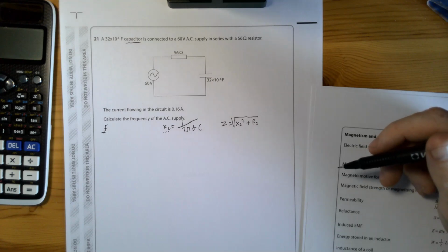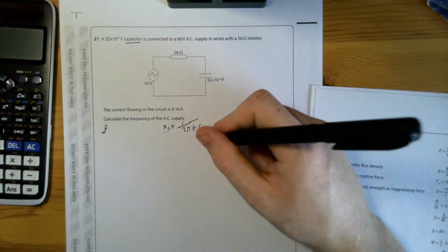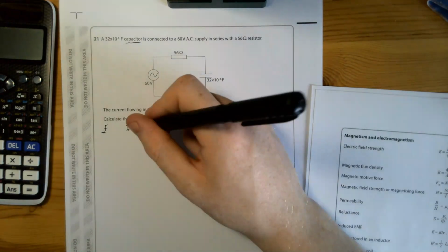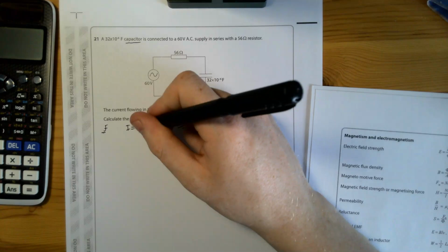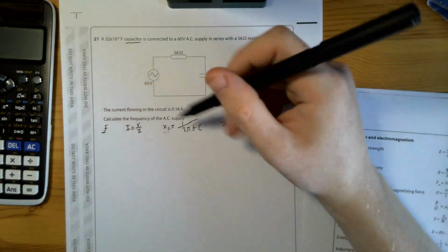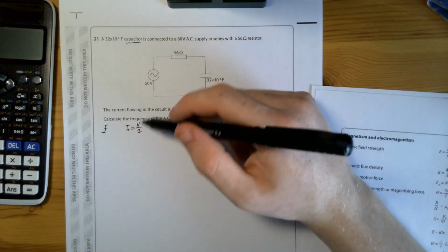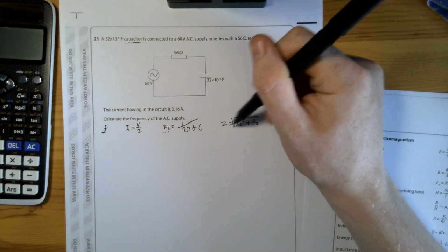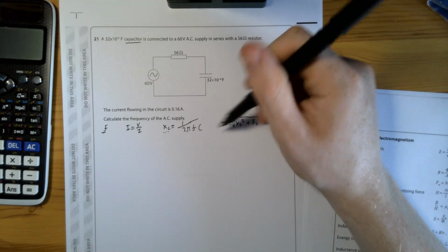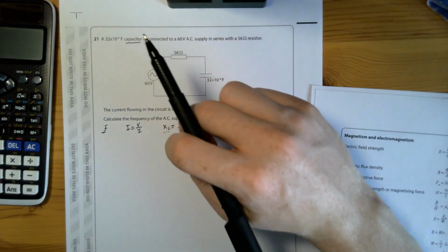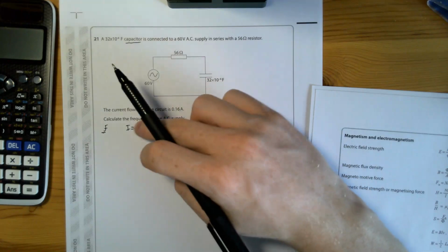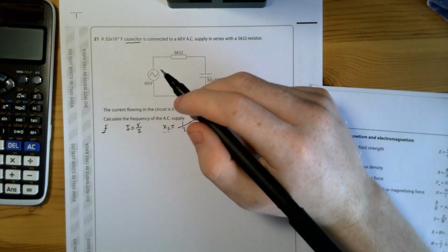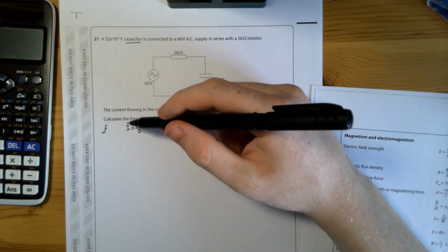Well, fortunately, Ohm's law for AC circuits includes this formula, which is the current is equal to the voltage over impedance. I do have a voltage, I do have a current, therefore I should be able to work out the impedance. If I've got the impedance, I should be able to work out what XC is in this calculation over here. Once I've worked out XC, I can then filter into here. So, right, I've got all the formulas I need because each formula only has one variable missing. And this is the one that's going to solve everything for me.